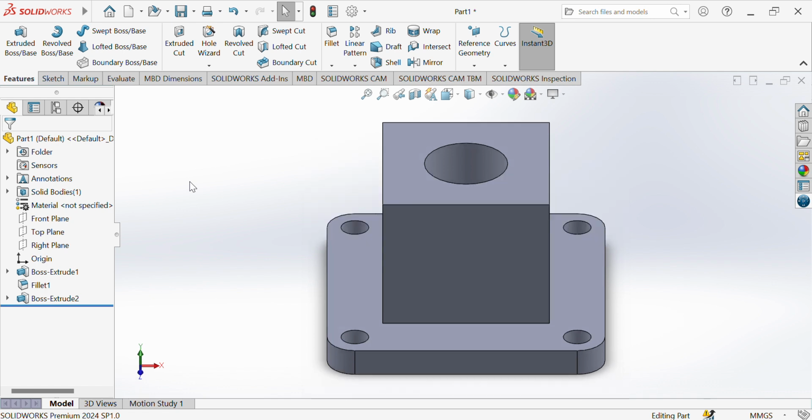So now let's see. I see this rectangle, but this one too also has curved edges. For my calculations, the full length is 60. I have a central straight space that is 30. That means you have what left? 30. 60 minus 30, equal on both sides. So 30 by 2, 15. So I'm believing that the fillet comes 15, 15 from both sides.